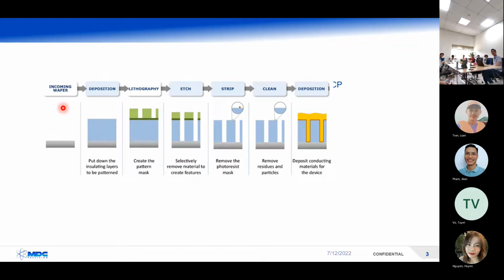Then we come to a Lam tool. Now, in this case, you have your conducting layer, you have your mask, and you have essentially the open areas. If you remember, I'm not going to paint, I'm going to sand away this blue material. So it goes into a Lam machine or an AMAT machine. Again, it's so small that there's not a physical way to do it. Let's say this is an insulating layer. The insulator is typically silicon dioxide, basically glass, okay? Silicon and two oxides.